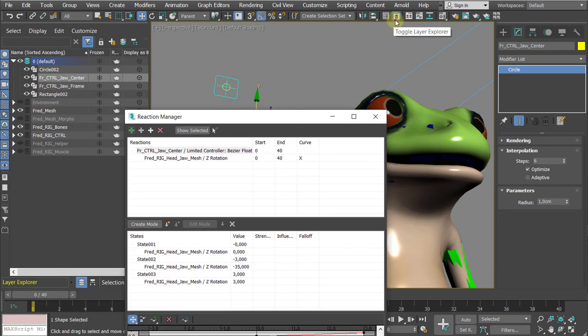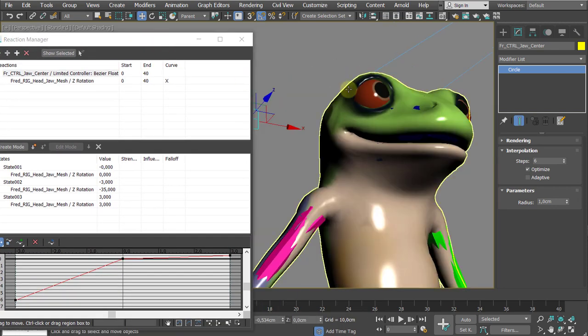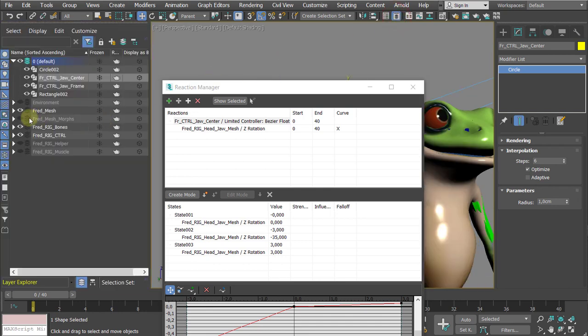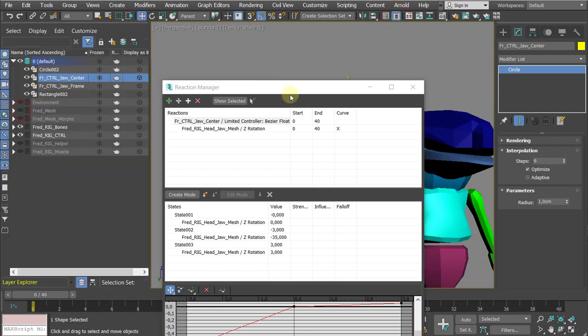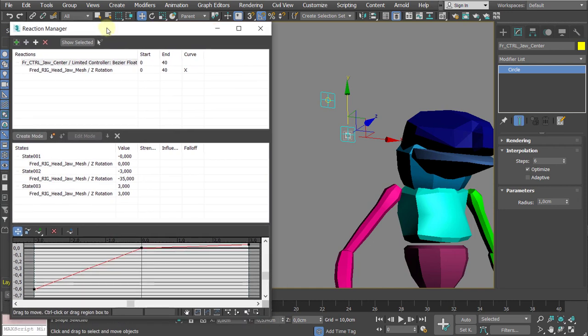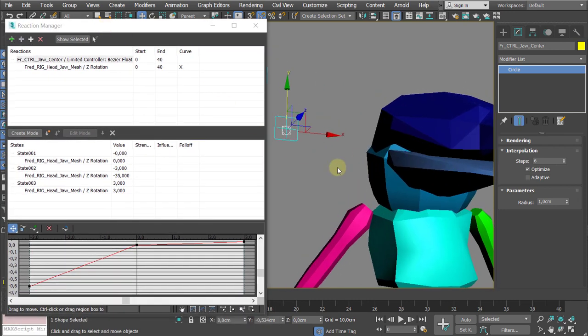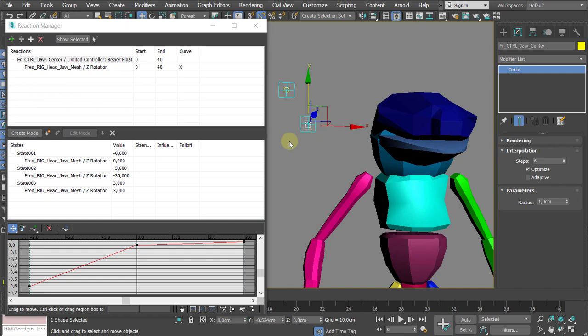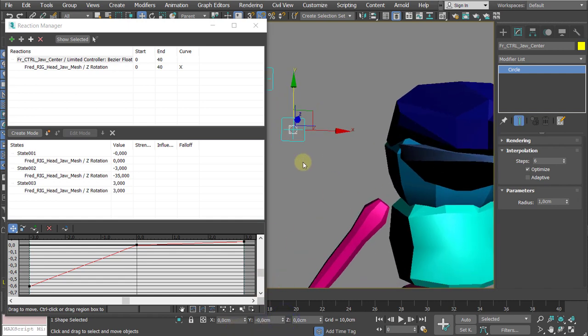Let me close the Layer Explorer, and it's time for us. Oh, sorry, Layer Explorer needed because we don't want to see the mesh. Red mesh turned off. And what we do want is to add some tilting movements and rotations on both axes. So going back, resetting it, and because it's a horizontal movement, so Y movement is done, we need a new master because it's a different type of movement of our object here.